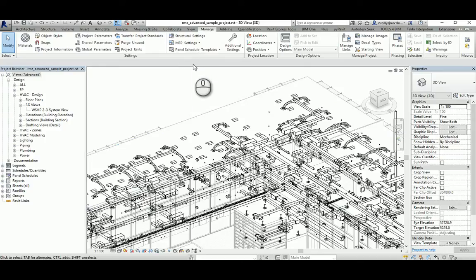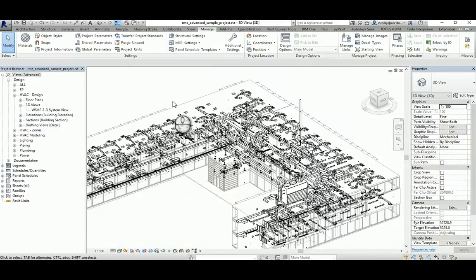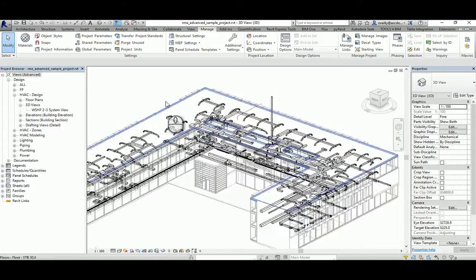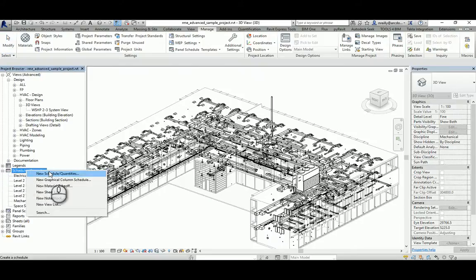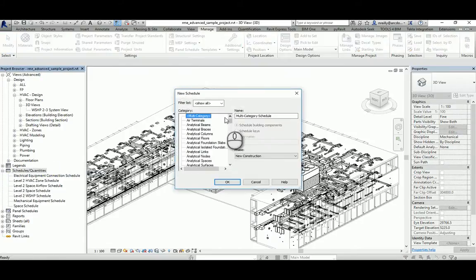And in the document we say that we think the best way to add the parameters is using the schedules within Revit or a 3D view. I'll show you the 3D view after I've done the schedules, so we'll come back to this view soon. I'll just go to schedules here, right click and new, and I'm just going to go with a new air terminal, and I'm going to put class in front of that just to split it out from the other schedules there.